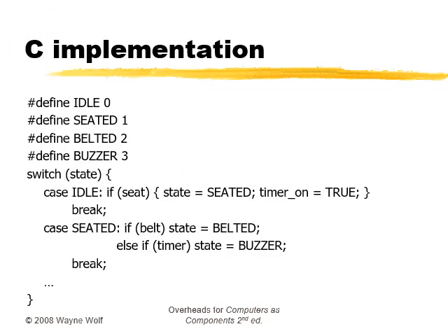This C code takes advantage of the fact that state will remain the same unless explicitly changed, which makes a self loop back to the same state an easy implementation. The state machine may be executed forever in a while loop or periodically called by some other code.